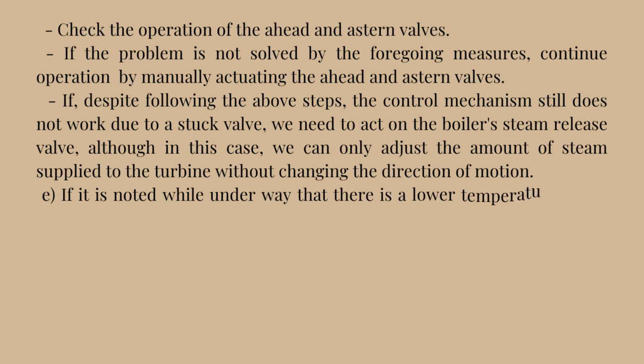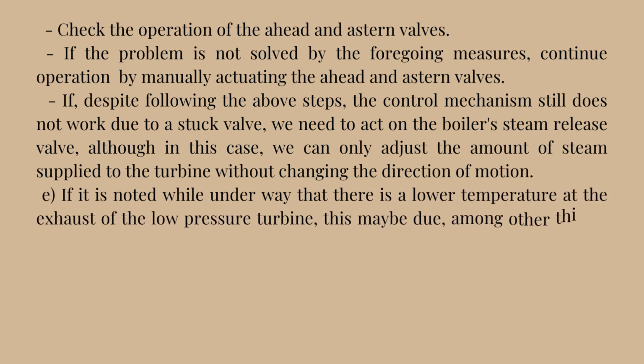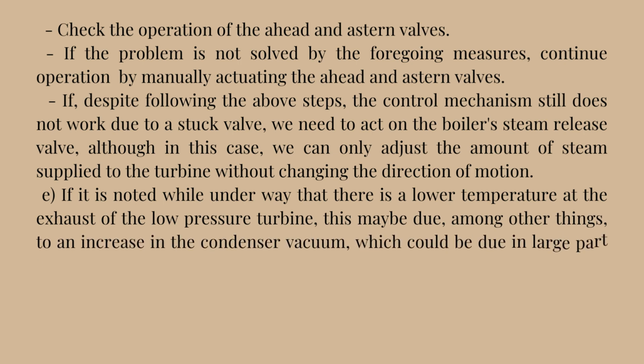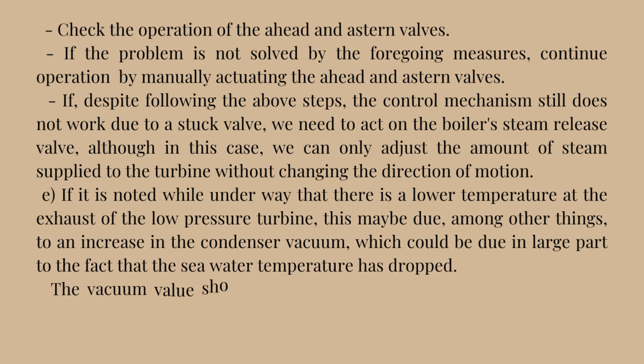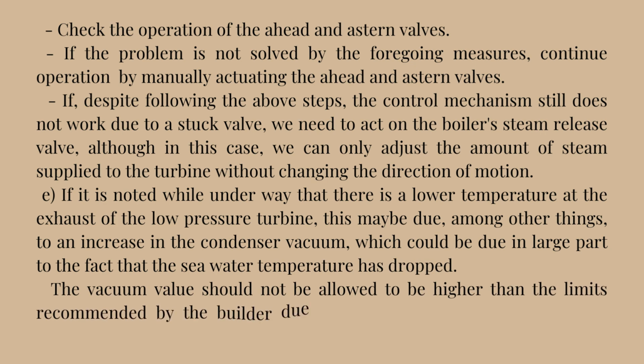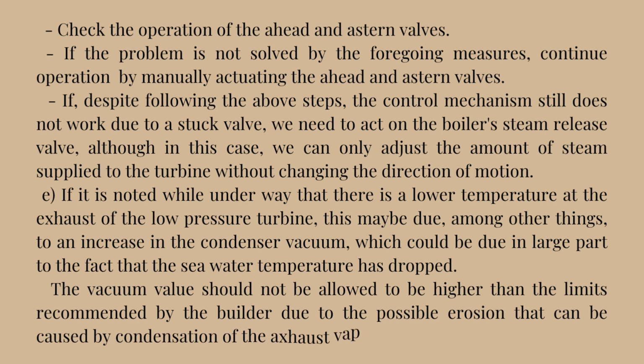E. If it is noted while underway that there is a lower temperature at the exhaust of the low-pressure turbine, this may be due, among other things, to an increase in the condenser vacuum, which could be due in large part to the fact that the seawater temperature has dropped. The vacuum value should not be allowed to be higher than the limits recommended by the builder due to the possible erosion that can be caused by condensation of the exhaust vapor rubbing against the blades.